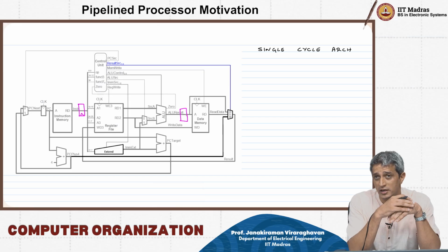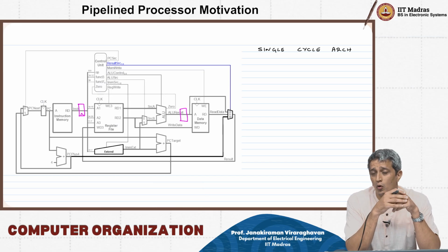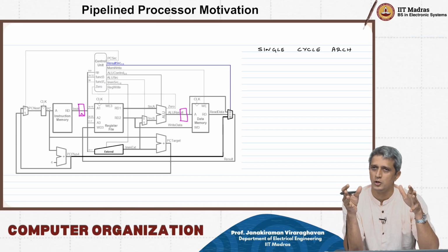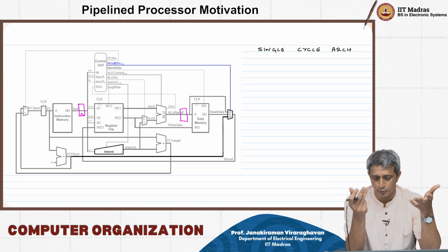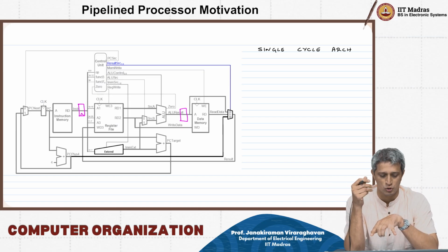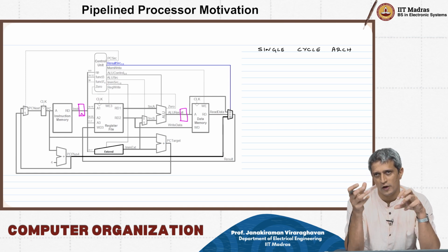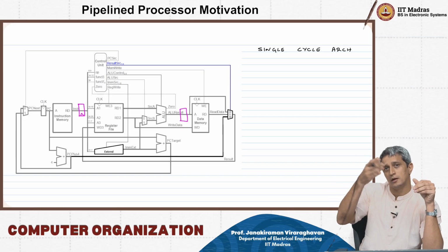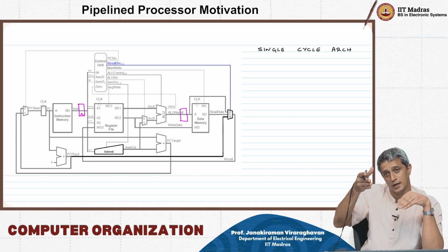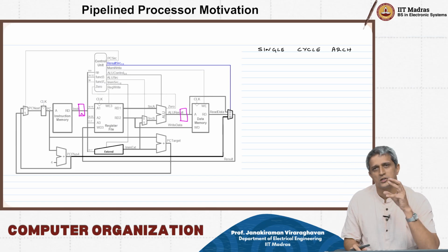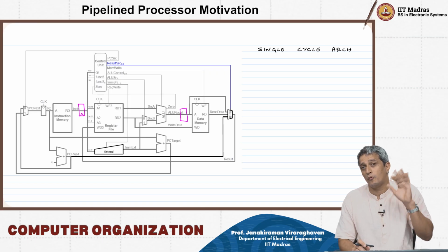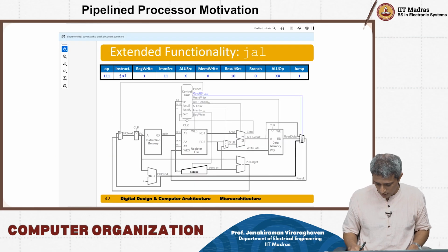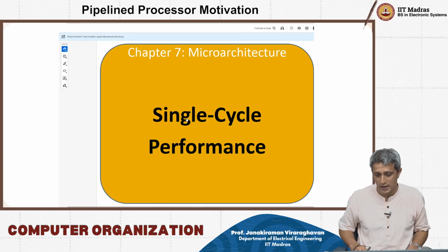By the way, in the multi-cycle implementation there is no necessity that you place a flip-flop after every single combinational block. You could combine some combinational blocks. For example, here I am assuming that decode, register file and ALU happen in one shot as one combinational block, and then I put a flip-flop after the ALU result. This will be a different multi-cycle implementation from what we discussed earlier, because of the place and the number of flip-flops used.